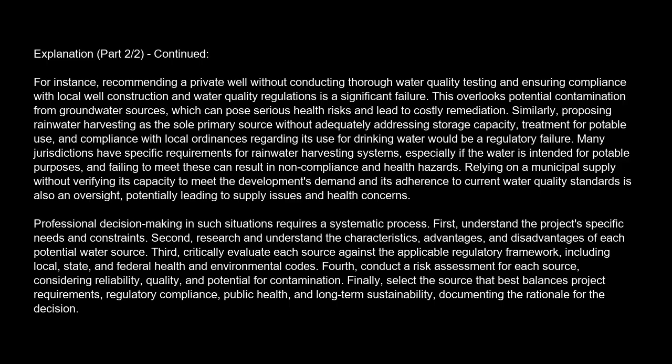Professional decision-making in such situations requires a systematic process. First, understand the project's specific needs and constraints. Second, research and understand the characteristics, advantages, and disadvantages of each potential water source. Third, critically evaluate each source against the applicable regulatory framework, including local, state, and federal health and environmental codes. Fourth, conduct a risk assessment for each source, considering reliability, quality, and potential for contamination. Finally, select the source that best balances project requirements, regulatory compliance, public health, and long-term sustainability, documenting the rationale for